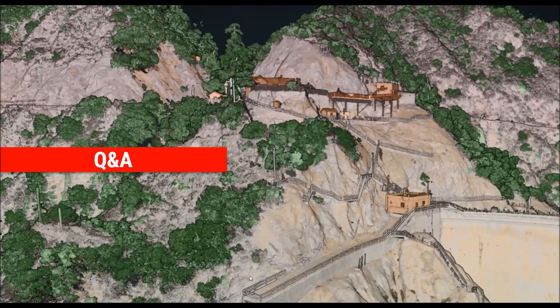I would say a single UAV flight, let's just say a single 15-minute flight. Obviously, the acreage is dependent on the scanner and the flight height. But LiDARSnap 4 processing with trajectory optimization, laser intrinsics, and ground control assessment and reporting would probably be done in about, I'm also thinking about my archaic computer, but probably about 10 to 15 minutes. The reporting may take another 10 minutes on top of that to calculate the residuals, but really pretty quick.